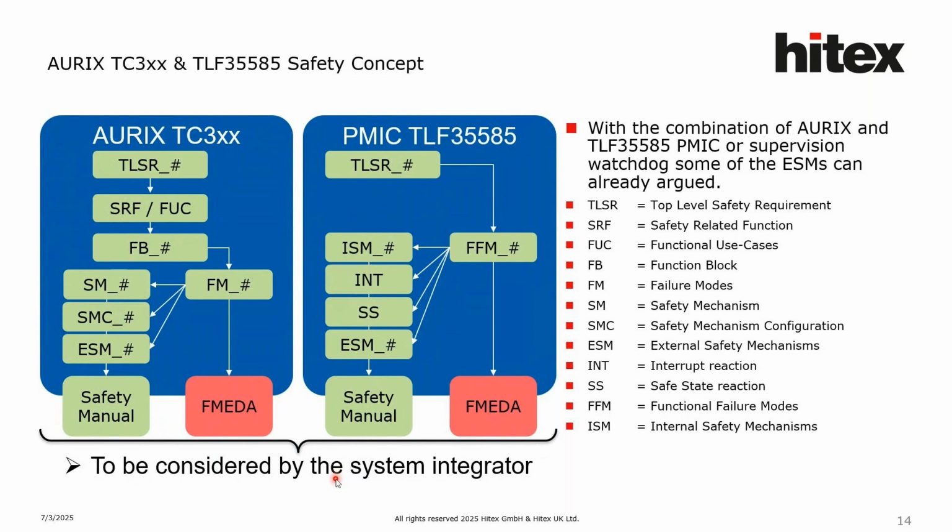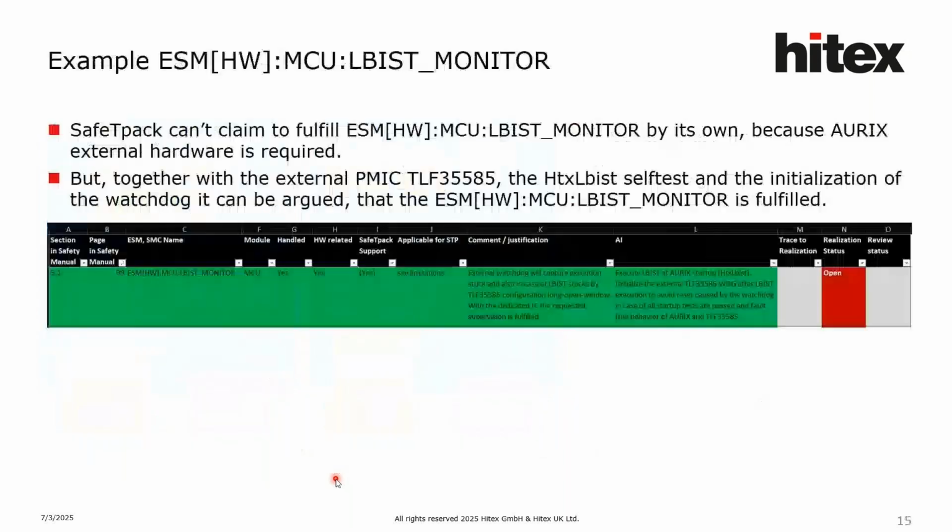achieved at the end. With the combination of both chips, it is possible to argue and fulfill, for example, the ESM of the AURIX safety manual related to the LBIST monitor. Because Safety Pack as a software product can't claim by its own that the ESM hardware realized LBIST monitor assumption of use is fulfilled, because a supervision and external hardware is required.